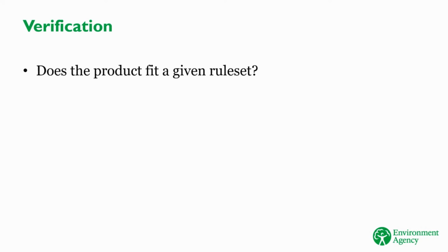One of the goals of BIM is to ensure that we can trust the information and data that we receive. There's no point in us storing things that are of poor quality, or in a form that we can't use. To achieve this, BIM introduces the concepts of verification and validation. Verification is a tool for checking the accuracy of data. It checks data against a defined set of rules, to check that it's reasonable. In other words, verification is checking that the product basically looks right.